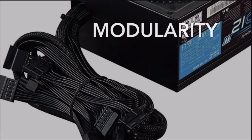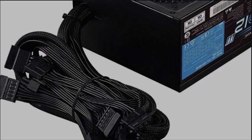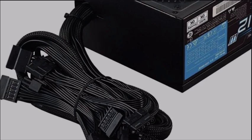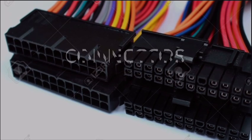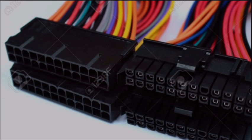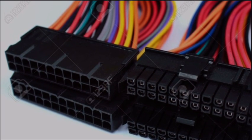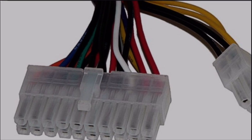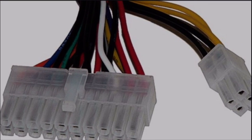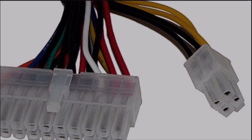Modularity. Some PSUs offer modular cabling, allowing users to connect only the necessary cables, reducing cable clutter and improving airflow within the computer case. Connectors. PSUs come with a variety of connectors for powering different components, including the motherboard, CPU, GPU, storage devices, and peripherals. Standard connectors include 24-pin ATX, 8-pin EPS for CPU power, and PCIe connectors for graphics cards.